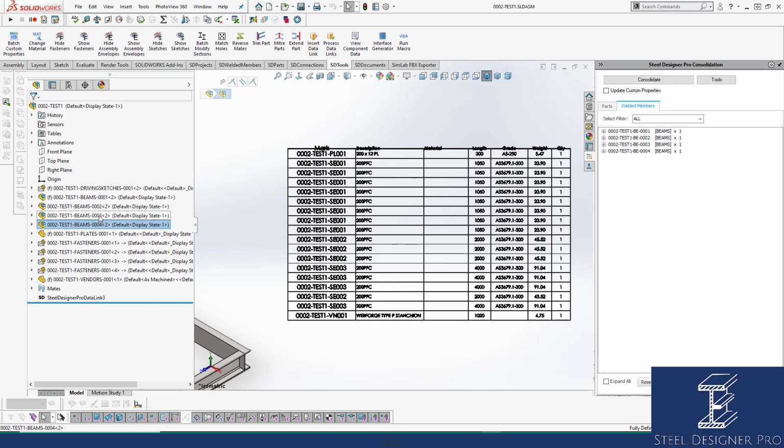If you do delete 3 and you put in beam 5 and it skips, and you want to follow your tree structure here also, you might want to use pack and go and bring it back in and then reconsolidate, and then it will automatically set this up for us. So be mindful that this information could be different to this information here, database and then file structure. The quantities for the items will also be collected over here as well. When we consolidate, this information is being placed into those items.